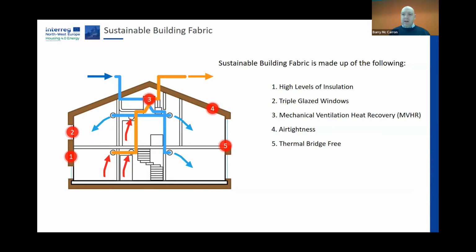But also, when modeling this in the building physics, it's really important that the surface temperature doesn't go any lower than 4 degrees from the design temperature of the room, which is considered to be 20 degrees. So we really need a surface temperature no lower than 16. And the passive house process has that baked in already. So that's the thermal bridging.